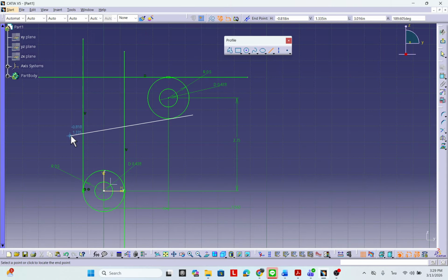If you need, you click on here. It's not good, right? Because it works as coincident with the V-axis, right? Okay, you don't need it. But if you never know, you click on here. Boop, it's constrained already. It cannot go far away from the center anymore, right? Because the constraint fixes this location along the vertical line and the V axis, something like this, right?